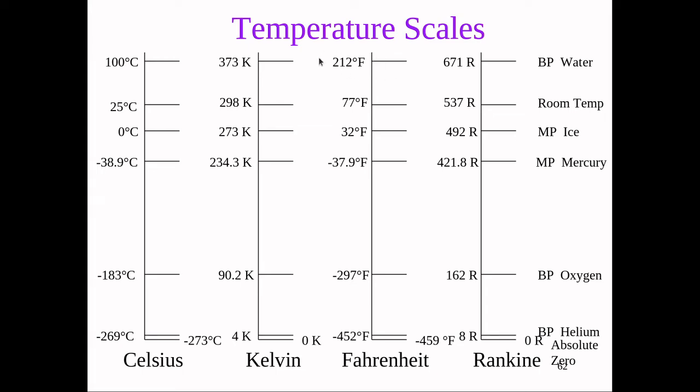It's 212 degrees Fahrenheit. And I'll even introduce this other scale here that we're not really going to talk much about, but it's called Rankine. The Rankine is the Fahrenheit equivalent to the Kelvin scale, where 0 Rankine is absolute zero, and each degree is the same size as a Fahrenheit degree. And so the boiling point here is going to be 671 Rankine. You typically only see Rankine pop up in some engineering texts. Sometimes they use this Rankine scale instead.